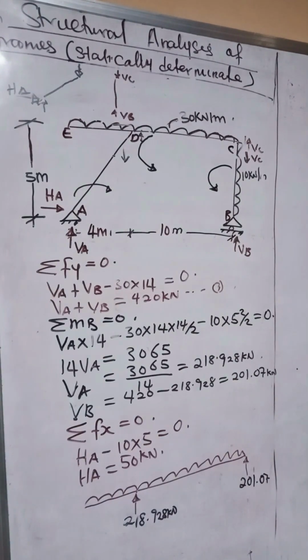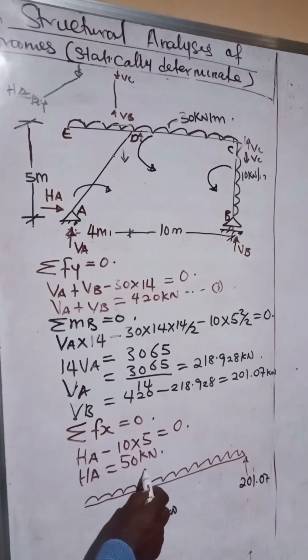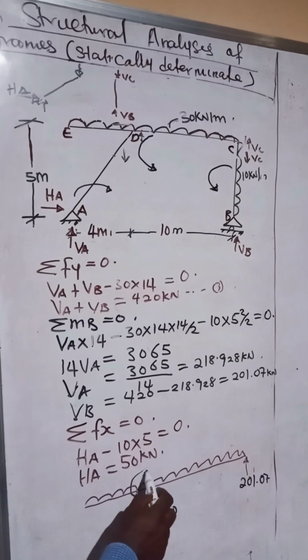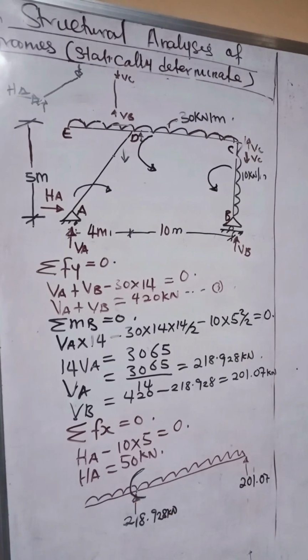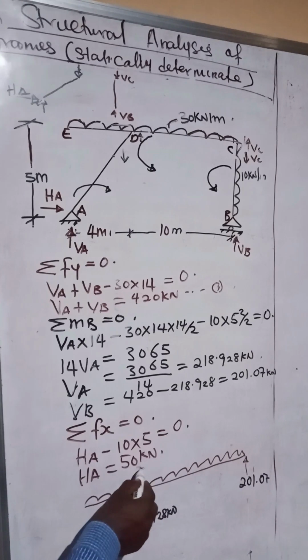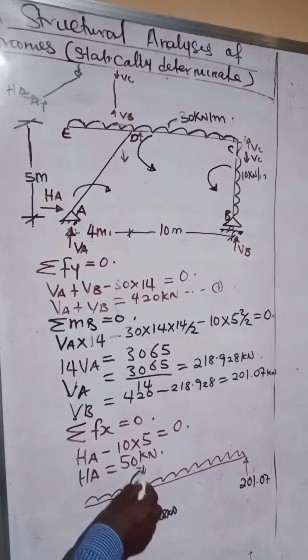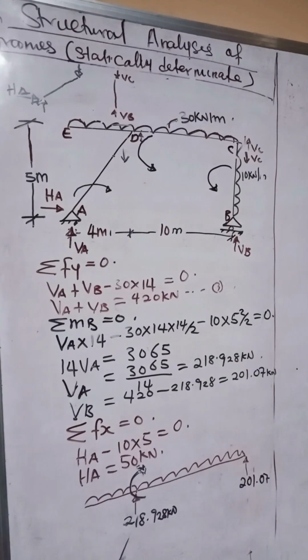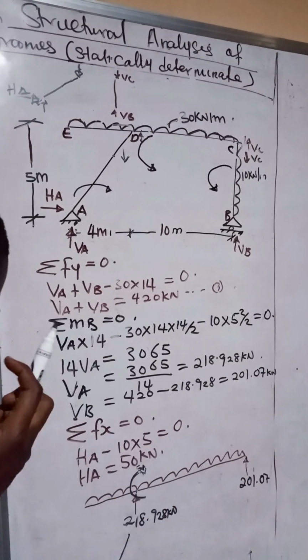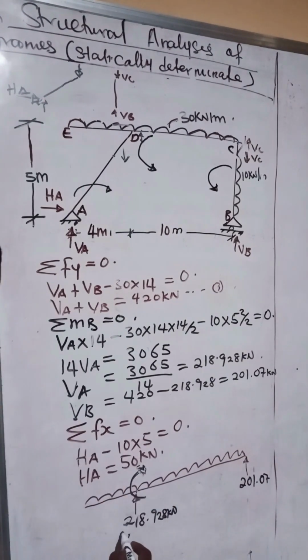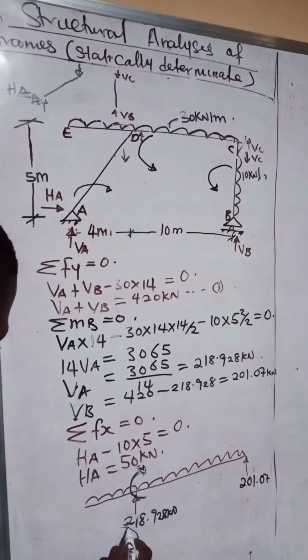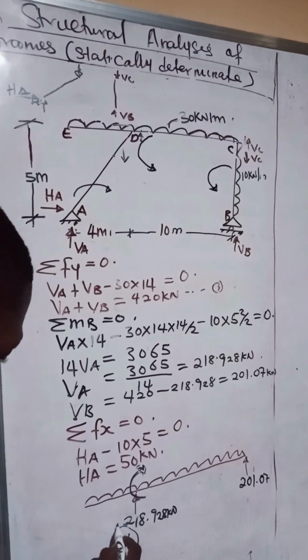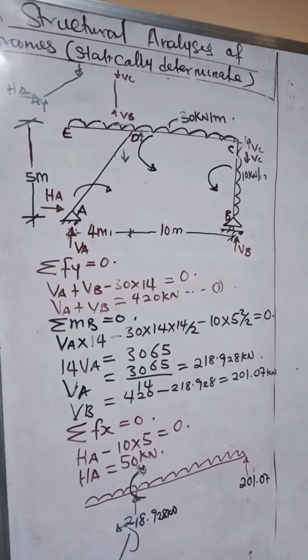Now the second part of it, now when we split it, of course we know there's going to be a moment here at the support. All right, so we're going to have a moment here. We don't know the value yet, but there's going to be a moment there. Now when we split this beam, it comes like this. Once this moment here is a clockwise moment, we'll have the same value for moment on this side of the column of the same magnitude.